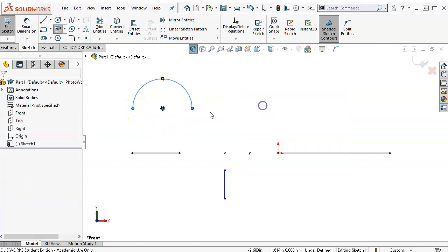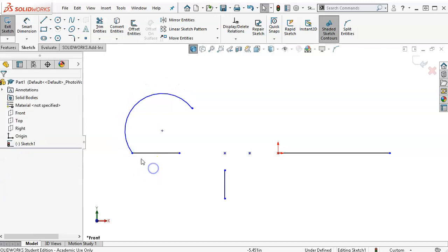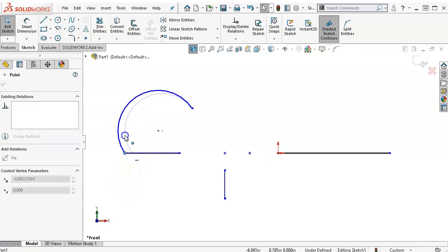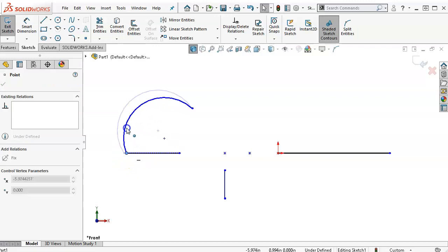Alright, so at this point, if I grab the end point and drag it to the end, I can kind of see that that has that hard transition. Also, since I did not make those coincident, it inferred a merge still. I did not know it would do that. So with the automatic relations, I did not expect that to be. So I picked up the coincident, and we see the dots.